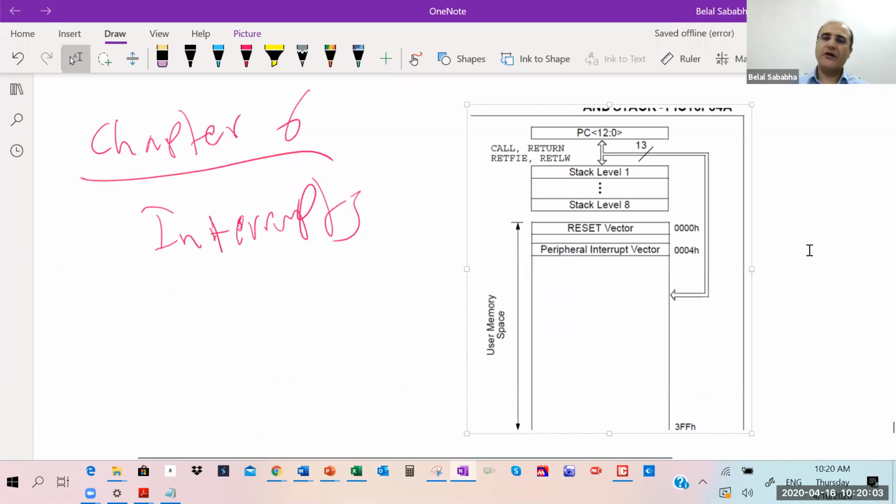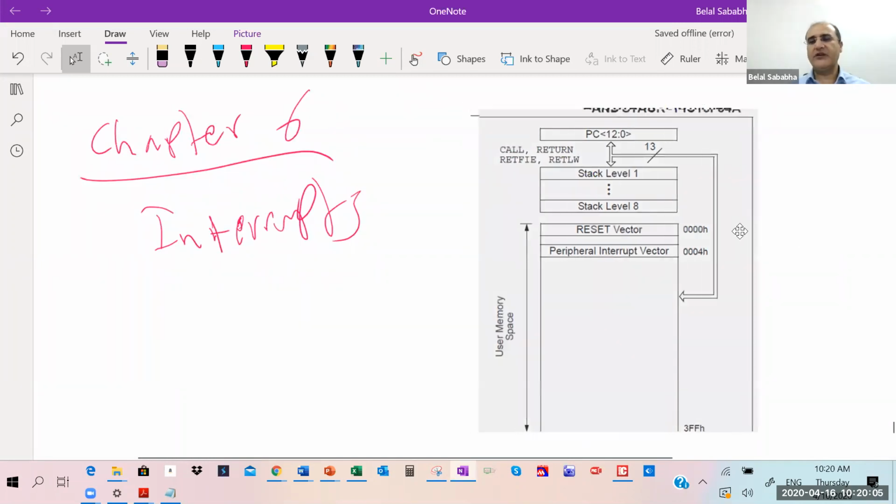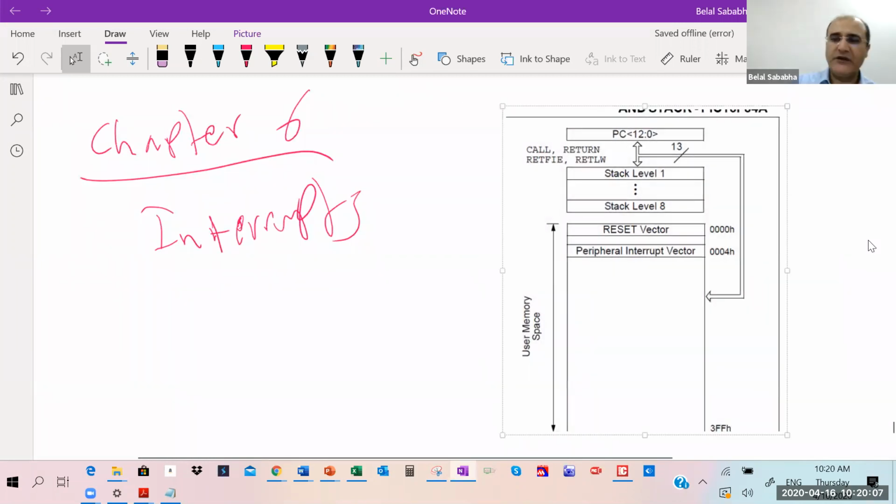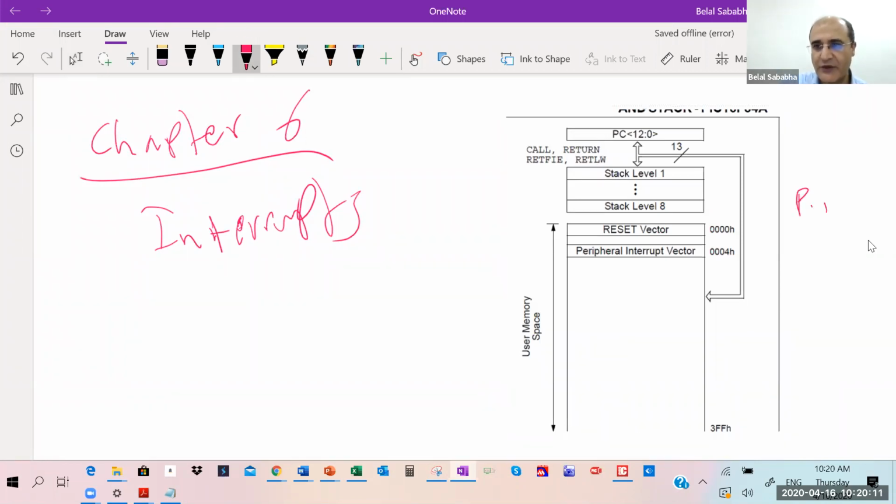So the way we write our program, remember, we start writing our program at the program memory, right? First instruction has to be here, and usually we say origin 0x00. So when we write our first instruction, it will be written here.